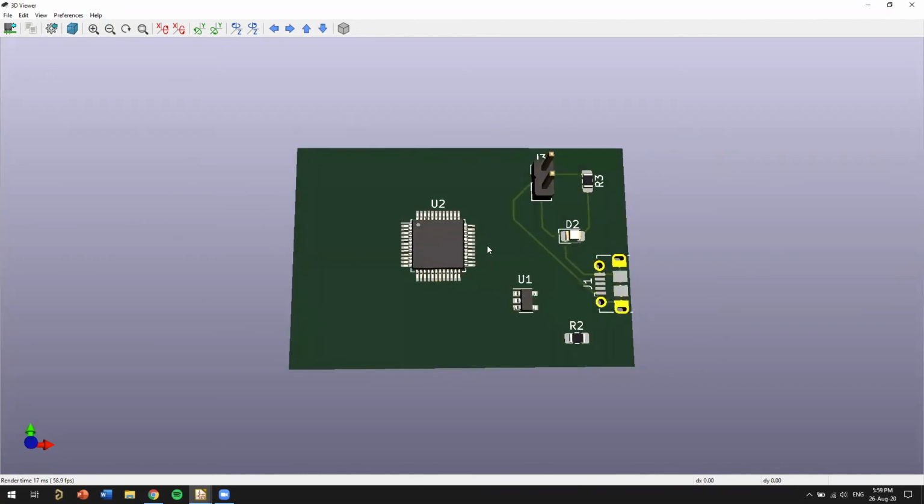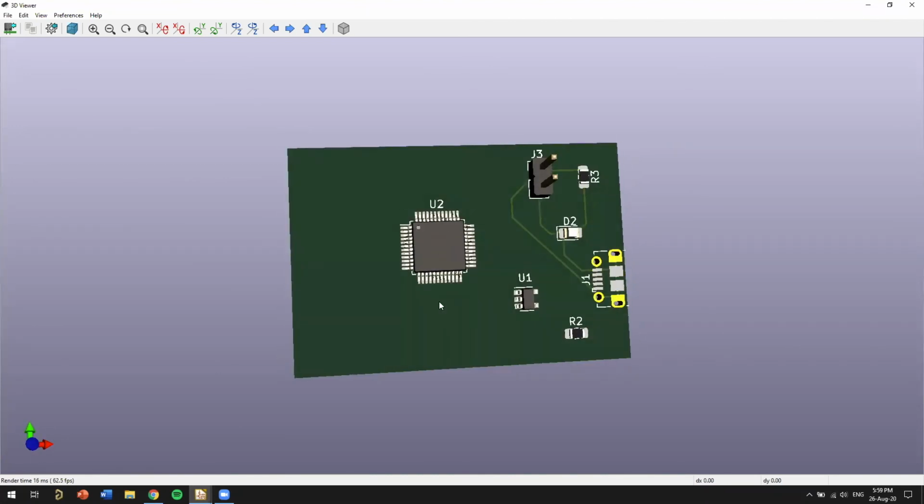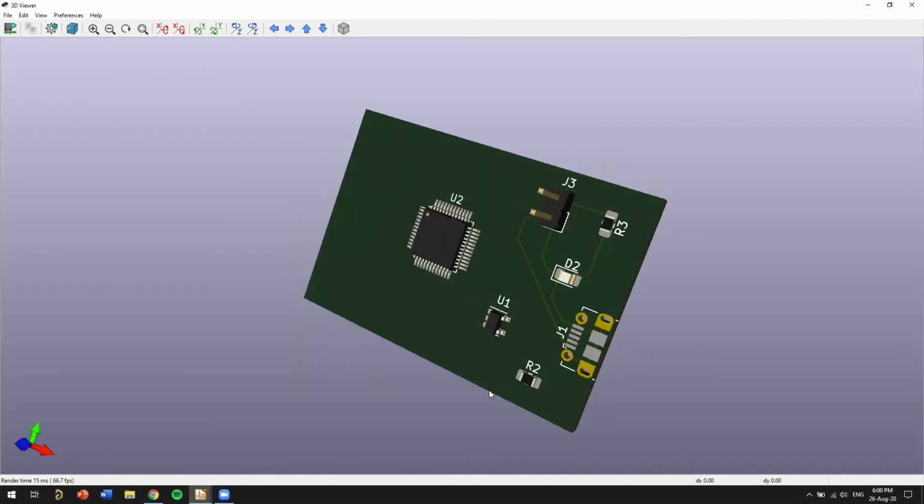And then this chip here, which runs on 3.3 volts, we're going to figure out what things to connect to this. We're going to want to connect, for example, a barometer to determine how high we are, an accelerometer to measure all the forces on the rocket as it's in flight, and probably some form of memory so we can log all of that data to a flash chip or something, transfer it to an SD card, so then we can connect it to our computer and analyze what happened in flight. We can see all of the different forces. We can integrate that to try and recreate the flight path, figure out how high it's gone, and then build on it from there.